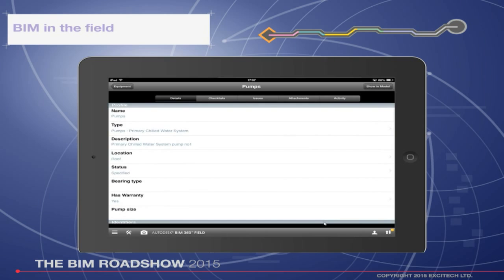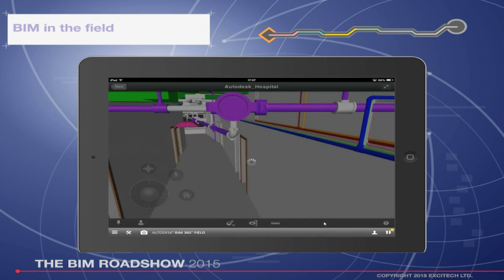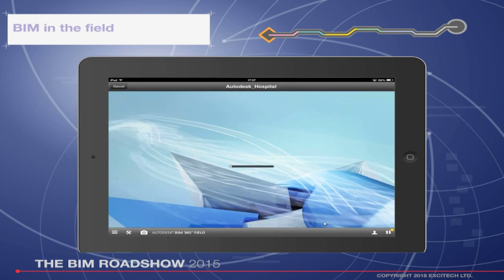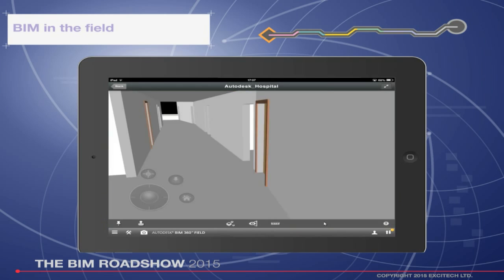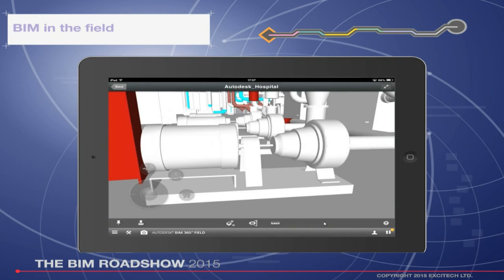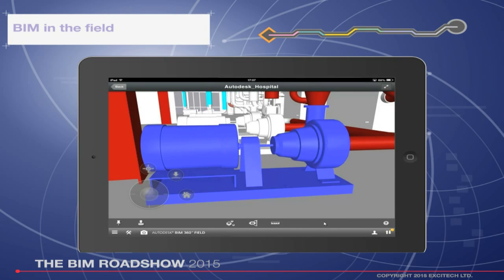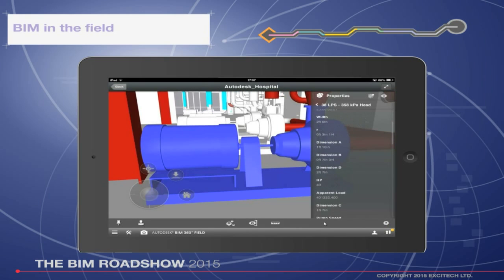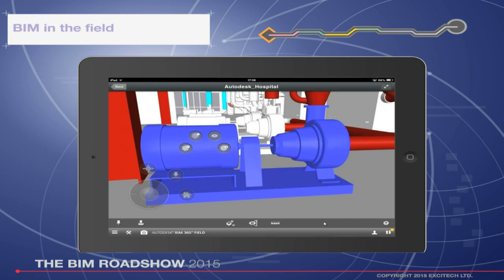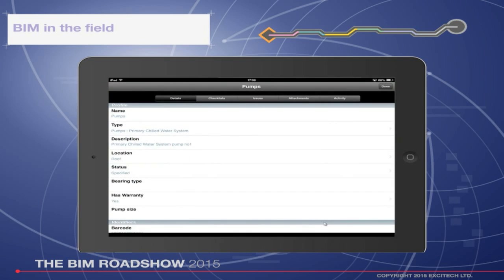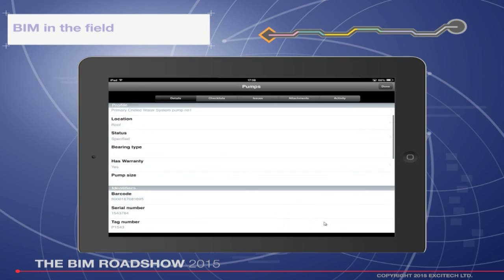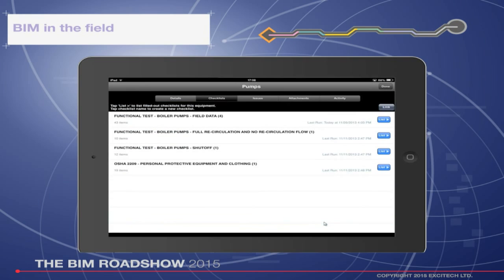There's actually other things we can do in here as well. We can click show model. So for that barcode, after we've collated the information, it's going to take me straight to the model. So I've barcoded the pump, I've collated the information of the pump as I'm commissioning it. There is the pump. I can now look round it, I can isolate it, I can look at the geometry that's come through from the modelling tool with my extra additional information. I can also look at associated documents that are linked to that pump. So there's lots in there, and it's really moving things forward.